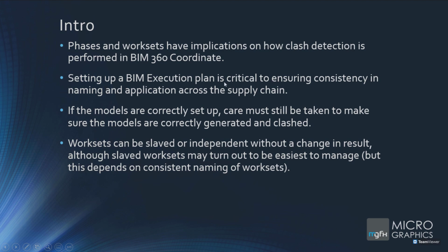The setting up of a BIM execution plan is critical to ensuring consistency in naming and applications across the supply chain. So if you're not familiar with a BIM execution plan, it's a document that is rolled out across the industry or across the supply chain, the different stakeholders in the supply chain, the different disciplines. And everybody then conforms to the standard that is required by the principal agent or the company that is responsible for managing that project.